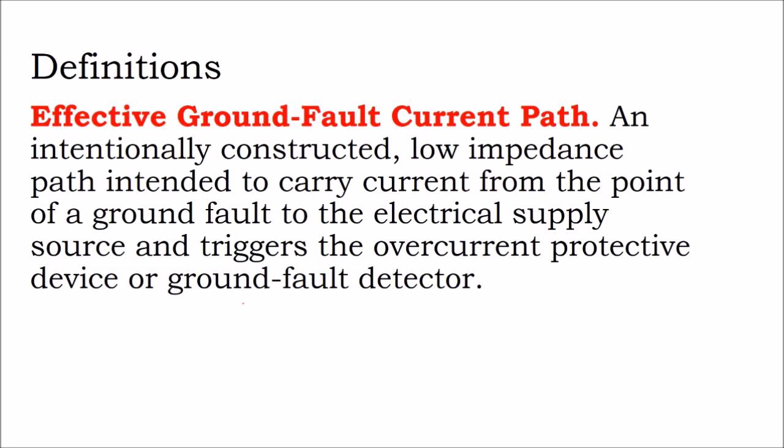How did the electricity get from the side of the building into the cables of the solar array enough to cause an arc fault to blow the cables apart? I was thinking, well, the module frames are connected to the racking, and the racking is a ground path, and the racking has a ground path that goes into the building girders, which are attached to the building, and none of those are considered to be an effective ground path. We have a piece of copper wire going up to the rack, then hanging over the side of the building and going into ground.